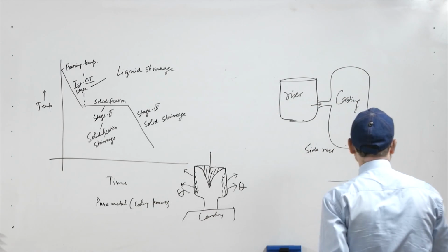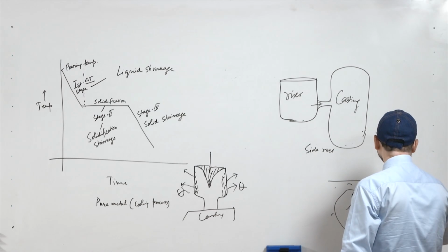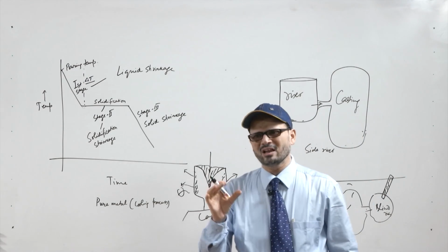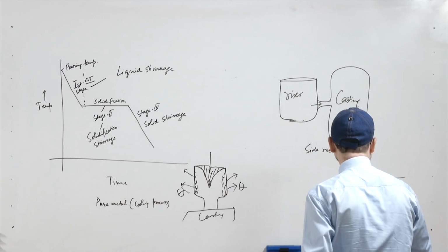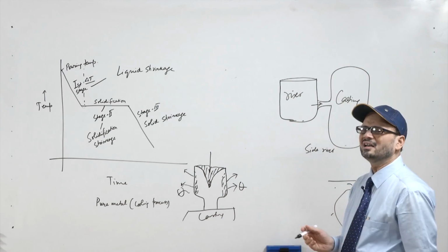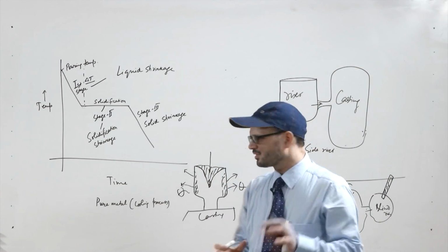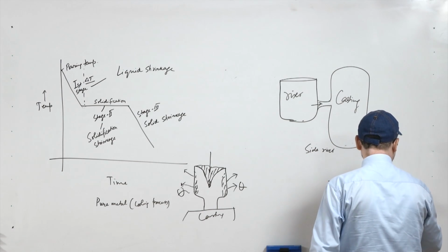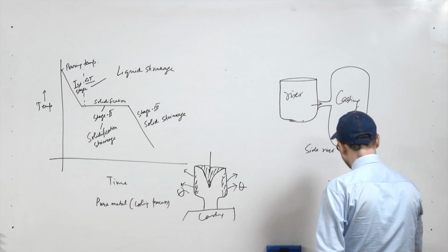That is sometimes known as a special type of core, and this basically helps in providing that environment because of which it is able to feed the liquid metal. And since it is covered, there is molding material on all these sides, so the sizes of these blind risers are small.